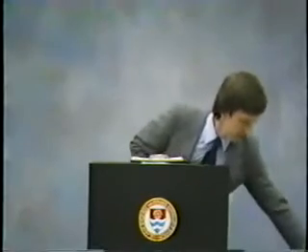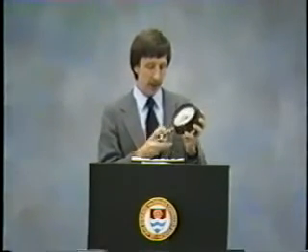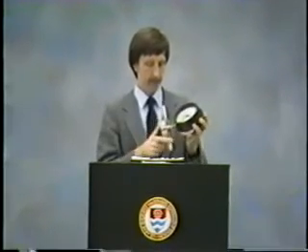So the best thing to do is, when you buy this equipment, if they happen to give you some of these inexpensive gauges, is to just get rid of the gauge and go out and buy a good gauge. This is typical of the gauges that we use. They have gradation marks at every psi. They're ANSI type A gauges. With these, you can get some pretty good accurate and precise measurements. All you do is connect this thing to the hydrant cap fitting. Get it good and tight and attach to the hydrant, and this will give you the kind of results you'd like to get.